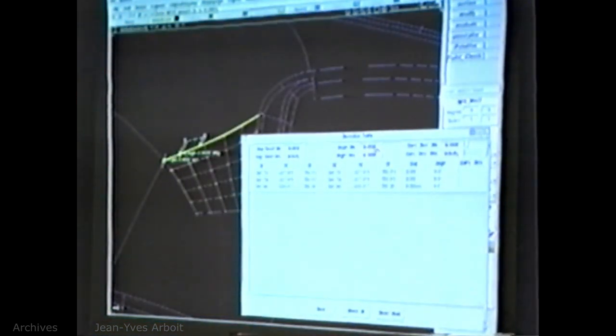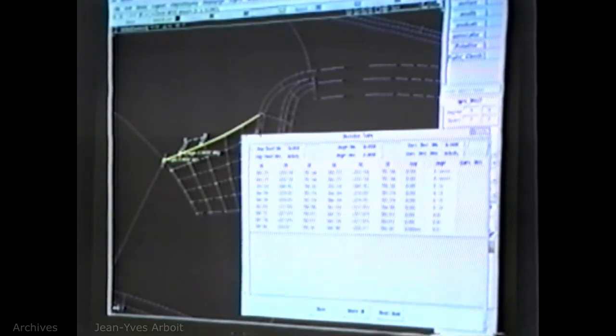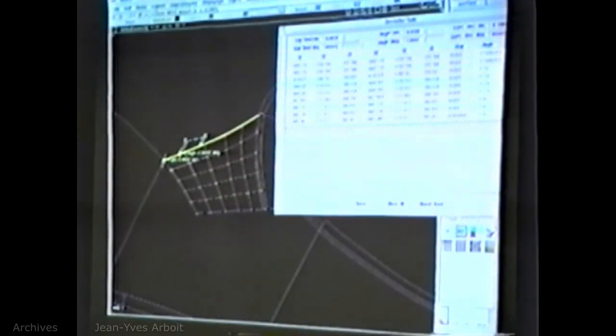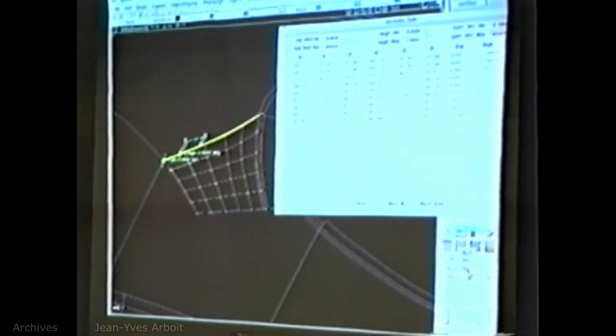Yeah. So in this case, by default, the deviation plot is, especially if you're measuring to a scan line, for instance, and you've got 1,000 points, it's going to measure for each point by default. So it's going to measure each and every point. And right now, if you're measuring to scan data, I don't think you can sample the deviation plot other than using this tool.